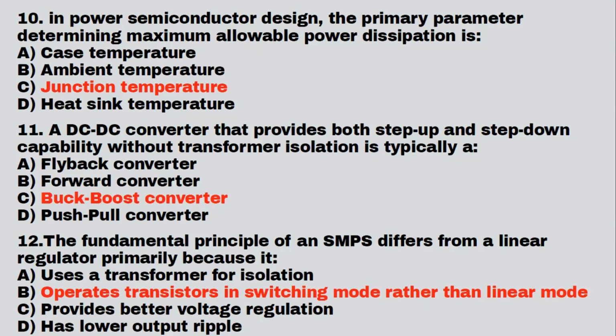Out of this, you have to understand. Okay, last question: the fundamental principle of an SMPS differs from a linear regulator primarily because it operates the transistor in switching mode rather than linear mode. This is a very important question. Please remember question number 12 is very important. You can refer to my other videos where I've covered power supplies, especially the SMPS.